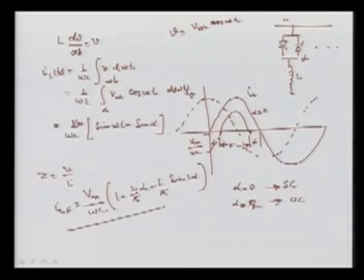Why is this a big expression? Because we are talking about the fundamental component of this current. This is a repeated curve, so we can go for the fundamental component, and then we get the ILF as this value. So we can get the impedance that is dependent on alpha. Once you change alpha, your impedance changes.